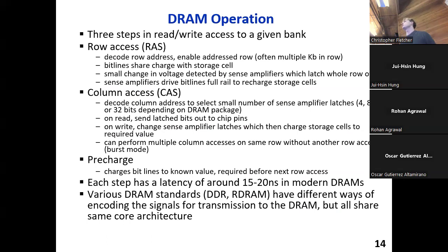We're going to do this thing called the row address strobe. The word strobe is kind of scary, but it doesn't really mean anything. All it means is we're going to send the subset of bits in our address that are responsible for choosing a row over the address lines, and that's going to kick off the process of opening a row of cells and getting the data dumped onto the bit line. So that's the first step of this operation.